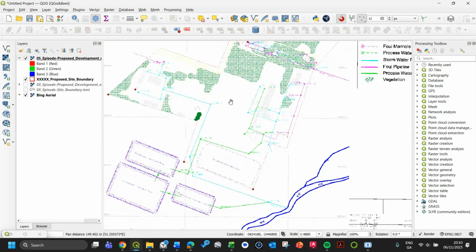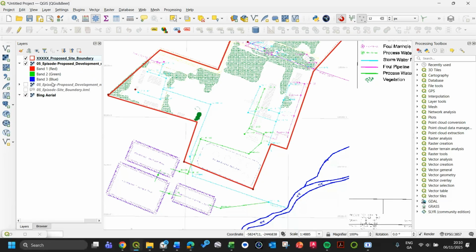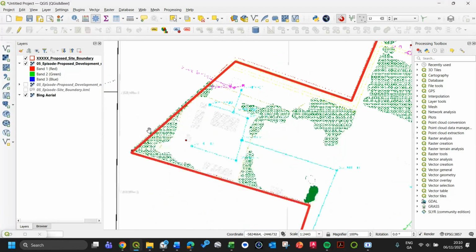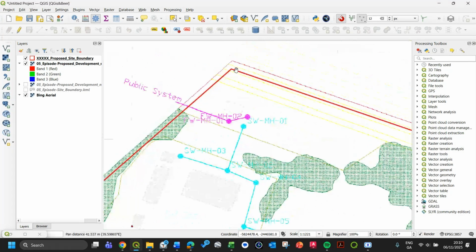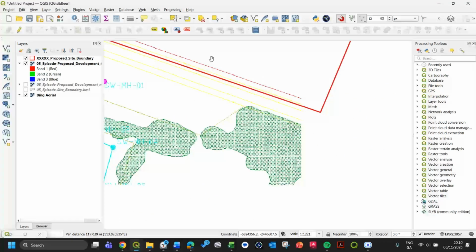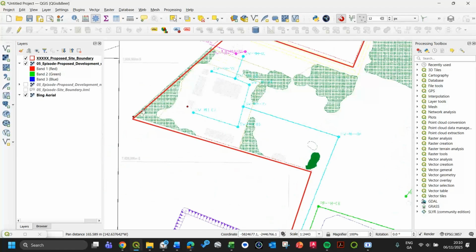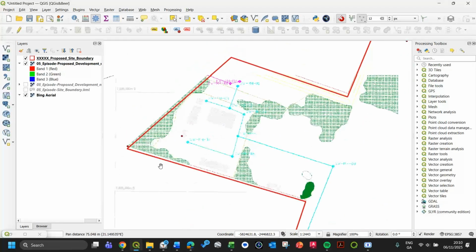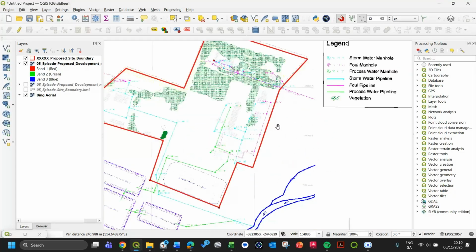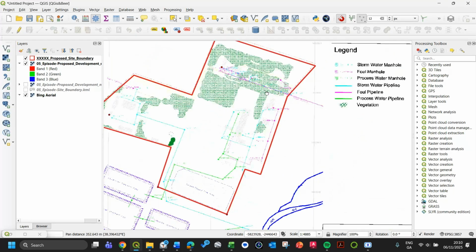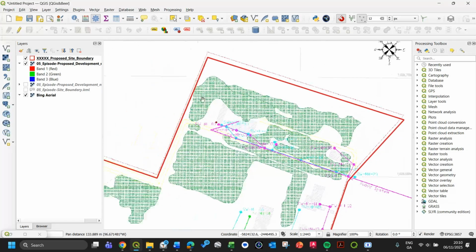Okay, so now we have our image well georeferenced as well, not based on the coordinates, but as you can see we have a slight difference between the real one and the image. That's because we had slightly poor control points from only the image, but again depending on the purpose it will work well enough.